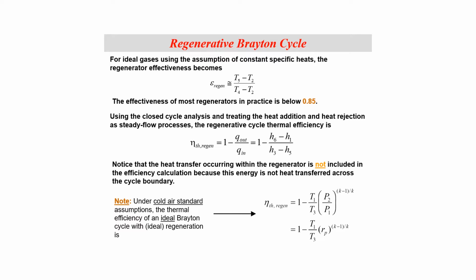Another thing we have commonly seen in Brayton cycles, because we are just dealing with air, is that sometimes we can just say that we are assuming the Cp to be constant, which results in us moving from H to T. So this is the same thing, they have assumed that Cp is constant, so they have changed the effectiveness to temperature terms. This is still relatively accurate. If you don't have the exact enthalpy terms, you can use temperature. It is sometimes effective for solving the process as well.